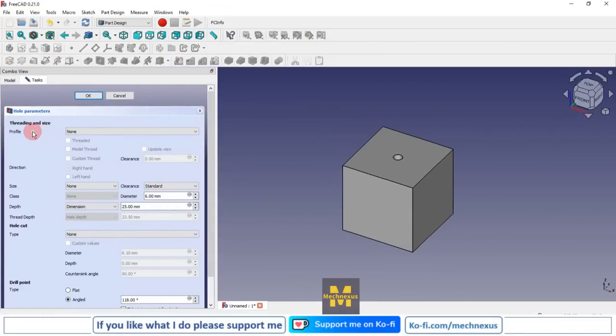Now here in threading and size, you will have multiple options like ISO metric regular profile, fine profile, coarse profile, UTS and UTS extra fine profile. So let's first select the ISO metric regular profile, and here I will select M20.